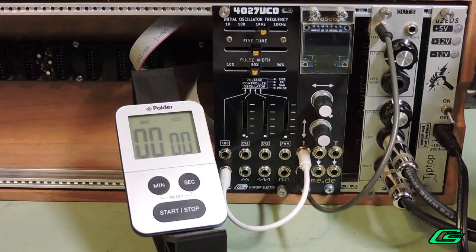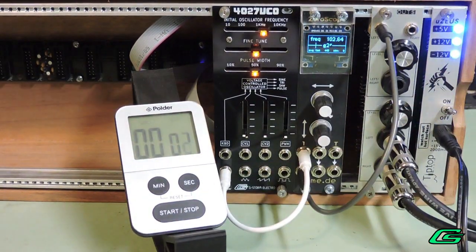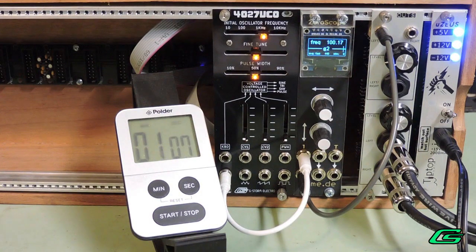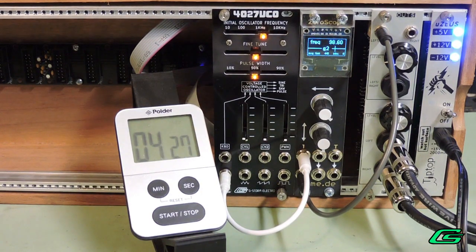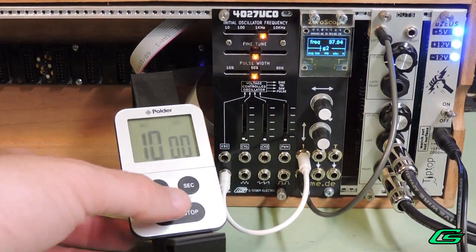If you've ever powered on an analog oscillator from sitting cold, you may have noticed the pitch is all over the place. This is called temperature drift, and it's normal for analog oscillators. Today's technology has come a long way with precise digital processor-controlled platforms. With analog oscillators, though, it's often necessary to allow 5 or 10 minutes for them to warm up and reach operating temperature, thereby giving the pitch a chance to stabilize. Digitally generated oscillators are generally not prone to temperature drift.